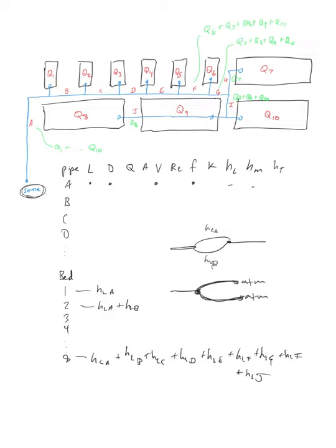And go through some amount of design to try to balance out the head losses, or at least build in a way that you could control the flow to these different outlets so that they could be approximately or close to what you want them to be, i.e. not all of the flow going to bed 1 with very little going to bed 8. How would you design this so that it's more similar?